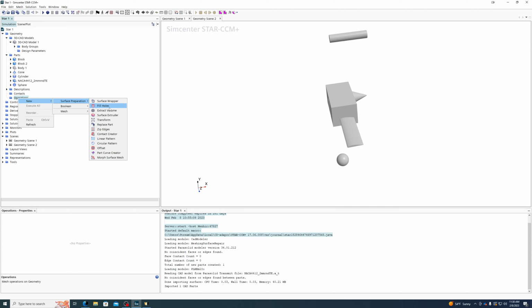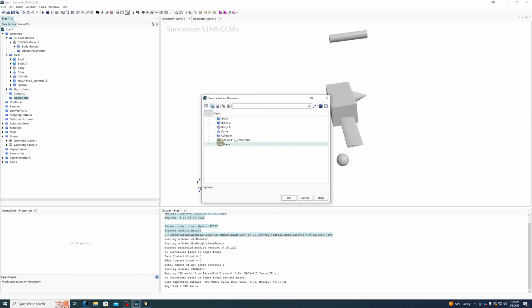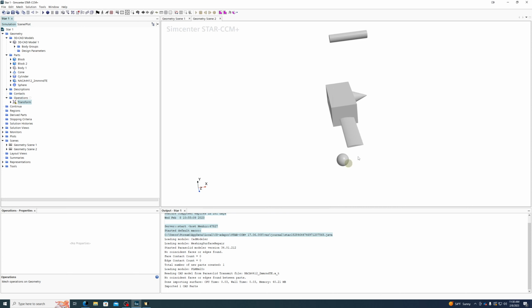So, if we want to, let's say, move a thing, well, that's a transform. We can select the thing or things, plural, we can select more than one, that we want to move. Let's say we want to move everything over 5 meters. Well, how do we do this? We select everything, and notice we have some properties down here that we can mess with.